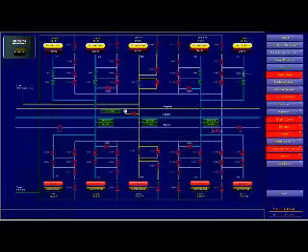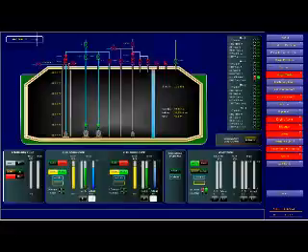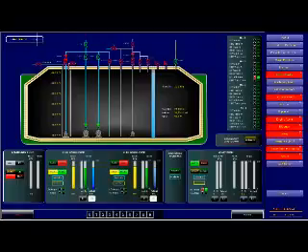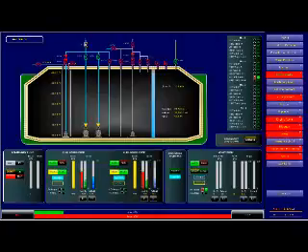Fair enough. So, what are the main points we have to take care of while discharging? Just that the pressure doesn't go up. Surge pressure is one of the key things which you will have to take care of. Okay, sir. Now you see you have only one tank on high level. All the tanks have gone below. And very shortly, are we discharging from number 2 tank very well? Yes, sir.